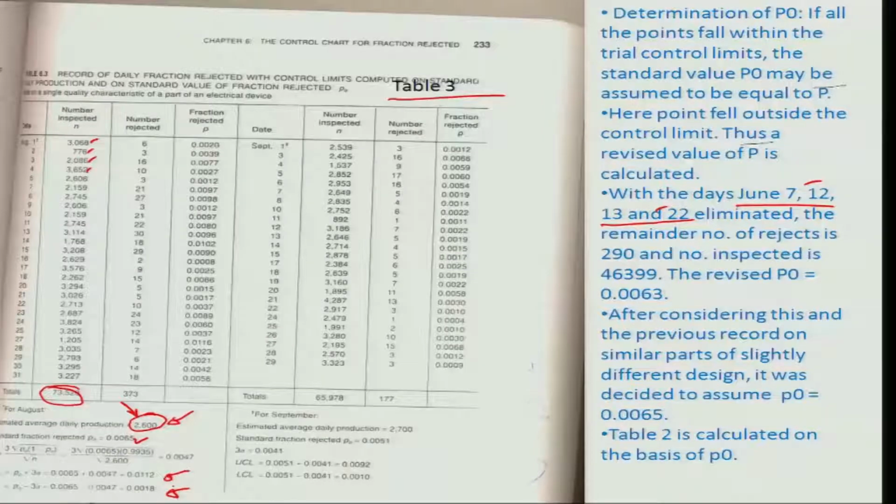So, this is a very critical decision-making aspect for the management, that when you want to straighten out your control limits, obviously you have to look at the number of outliers, or the extent to which the outlying capacity is there. If it gets minimized because of 1 or 2 iterations, that should be time enough for the management to decide that we now need to have straightened control limits, and then you can calculate everything on the basis of the average daily production.